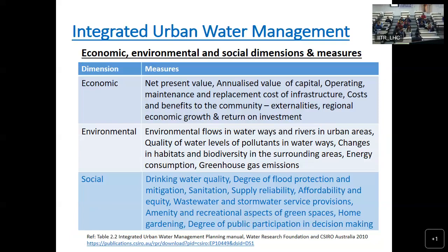Now everybody agrees that roads are required for development. But if you take major roads which are coming up, in many places, very high embankments are constructed. Now, these embankments, if you do not provide sufficient drainage passages for water to be taken from one side to another, they serve as just earthen dams.